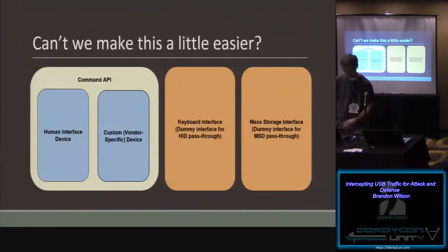All right, so that's great and all, but I don't want to have to re-implement the entire mass storage protocol and the code to handle the file system stored on there. It would be nice if we could get the host OS to handle all that stuff for us. So for specific scenarios such as mass storage devices, there is an option. We can make the Arduino expose an additional mass storage interface and push any mass storage traffic from the device straight to that interface. That way the PC just sees another drive and it can do all the work for us. So you can see I've got two interfaces there, a keyboard one and then a mass storage one.